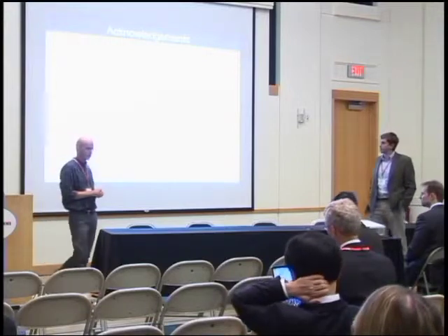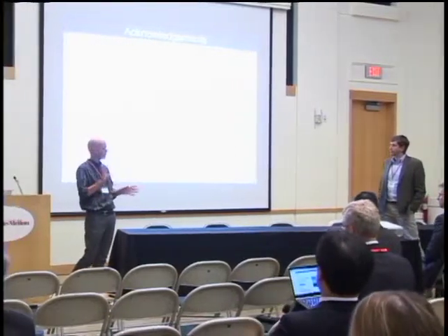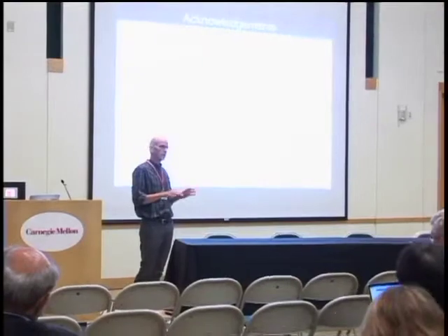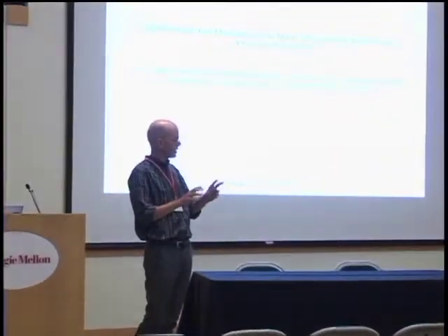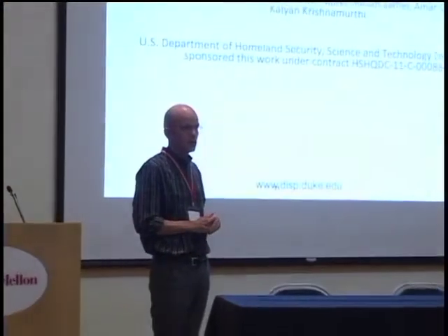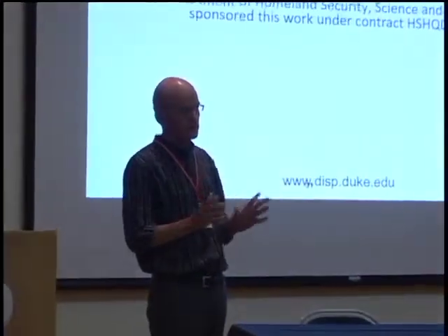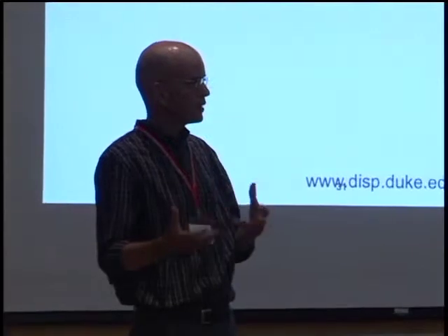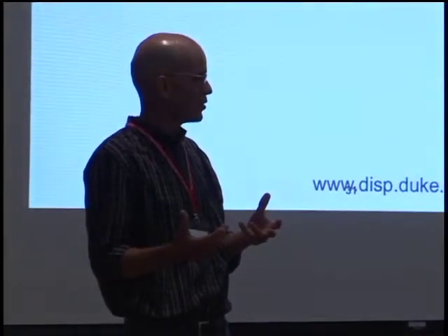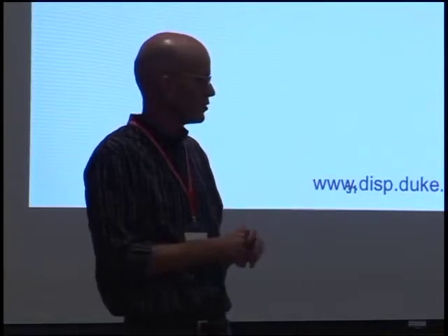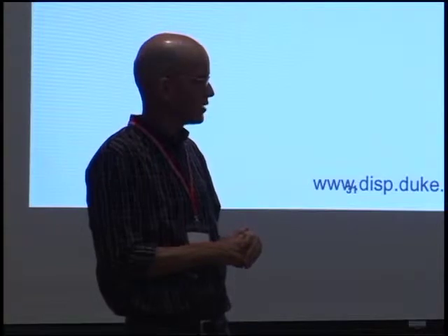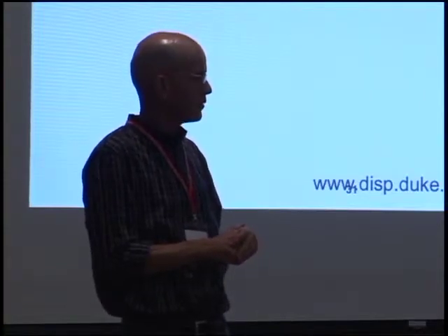One of the ways to think about that is compressive measurement on what nominally is non-compressive data, because essentially the way people tend to deal with speckle is to try to average it out, take some block and average. Another way to think about it is that if you measure an image that has speckle in it, it's not as many measurements as you think it is. And that's what averaging is doing, but you shouldn't average based on just a local average. You should average on some kind of compressive kernels. And that gives us some very nice results, actually, for smarter averaging, for despeckling, basically, of data.